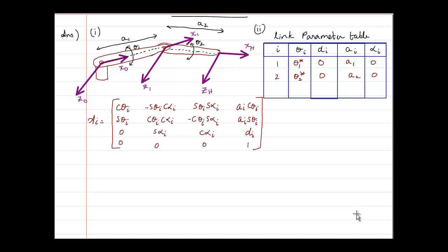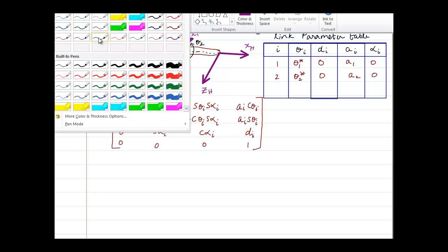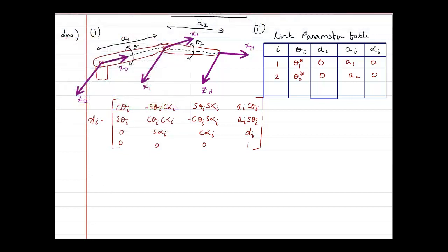So this is the equation that we use for writing the transformation matrix for each row of the link parameter table. So without wasting time, we will straight away go and write the equation for a1. As we already know, we have to put the equations of theta, alpha, d and a1 here. In the first row, it is theta 1, so I will write cos theta 1.